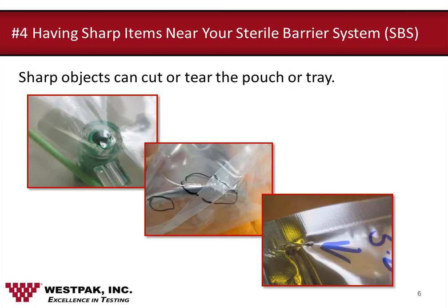Thanks, Tim. So Jared, if you're talking about how you determine your minimum peel value, when you do your IQ, OQ, PQ of your sealing equipment, you'll have your nominal seal value, and you would take that as your minimum seal value that you want to test to. So when you do your accelerated and real-time aging, you can then check it back against your real-time samples. So, Tim, any more questions?